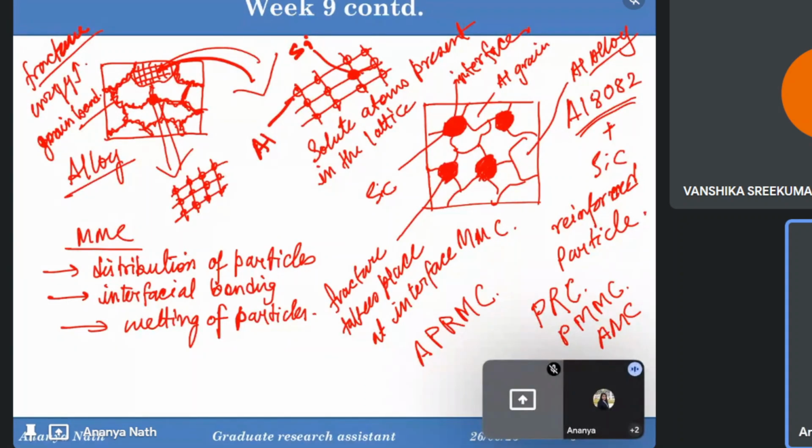So we can get the thermal conductivity, electrical conductivity, strength like the metal, and at the same time higher strength modulus, low thermal expansion, wear resistance, these types of properties of the ceramics or the reinforcement particles as well. For aluminium, as aluminium is known for its low density, we can get very low density in case of aluminium metal matrix composite, because we are adding some extra material in the parent metal, so obviously the density will increase, but as aluminium is already a low density material, the AMC will not have a much bigger density value like the other metallic MMCs.